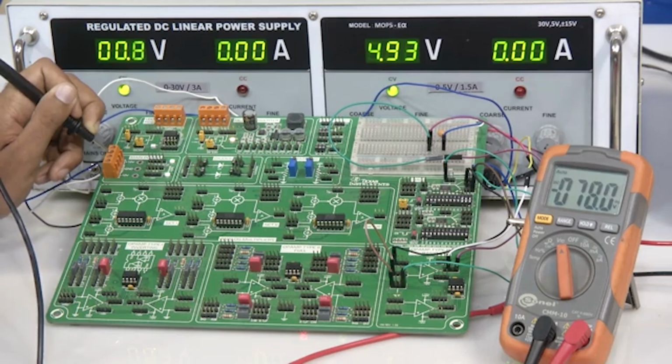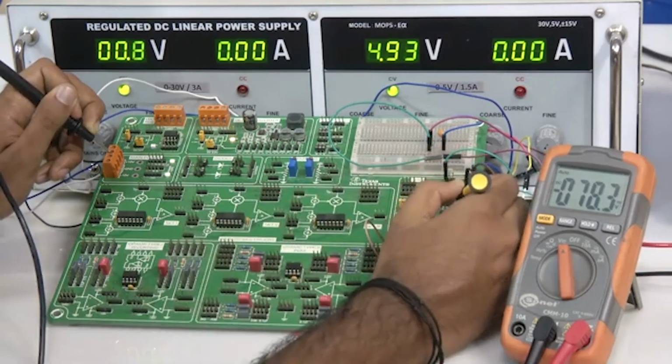Because of that we are seeing this change. So we jumped from around 37, because earlier it was 2 raised to 0, 2 raised to 1, now it is 2 raised to 2, it is almost doubling from 2 to 4 the weight of that bit. Because of that we had 37 millivolt, and we came to roughly around 78 millivolt. Now let us change the next bit and see what we are getting.